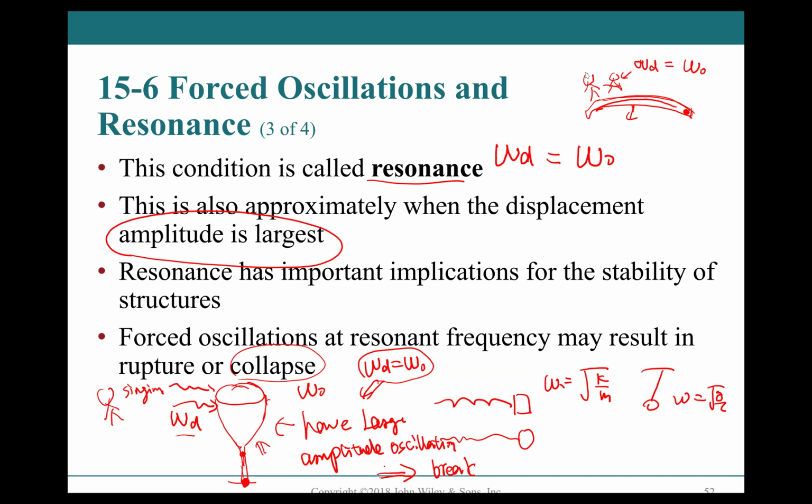If you do a random frequency, see this. Will anything happen? No. I have a better pencil. Only when you apply the force at the right frequency are you going to have a large amplitude. If you do it randomly, then no large amplitude. Right frequency, then large amplitude. This is also when resonance happens. You have to apply a force at the right frequency to make the amplitude large.